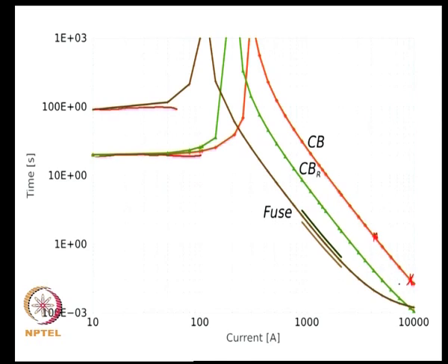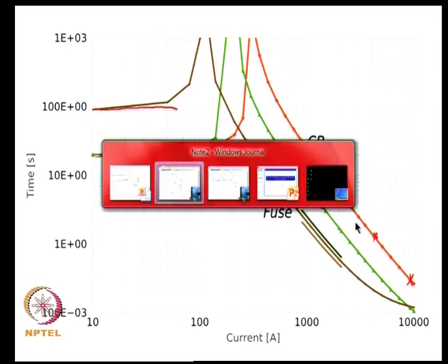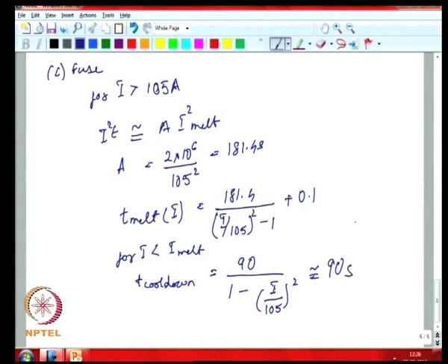You are looking at each range: would the curve in the upstream zone be lying above the curve corresponding to the downstream zone? Actually plotting these protective characteristics in a time versus current curve gives you a good feel for whether it is coordinated, what the margins are, etc. It gives you an overall picture of what the situation is.